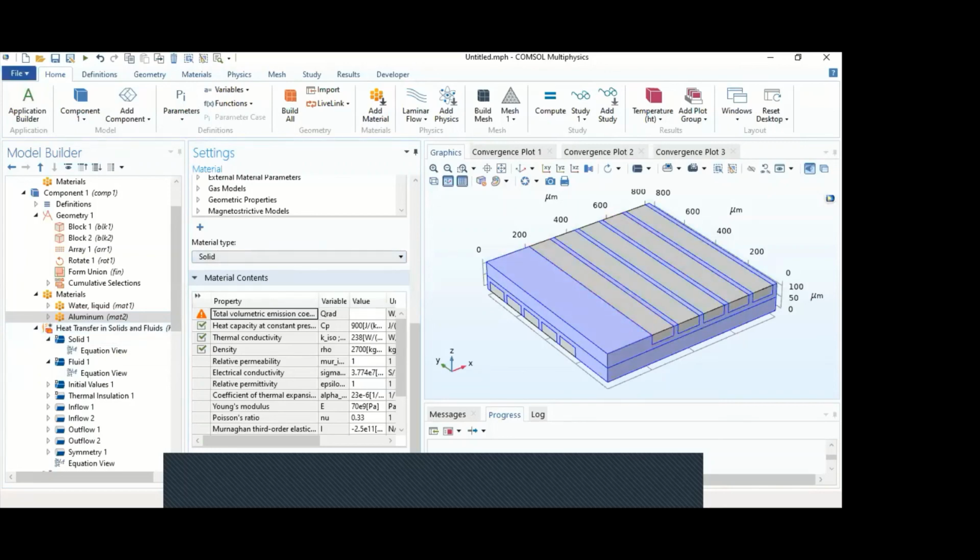As for the other question, we have another question. How can I get the best mesh for each surface which gives the best accuracy? You can refer to the user guide. There are lots of meshing techniques you can use, but basically we try to cut down on the number of mesh elements, but at the same time not create anomalies in the results. So if we have a very coarse mesh, we can find lots of anomalies in the results, like the transition between one value to another can be jagged.